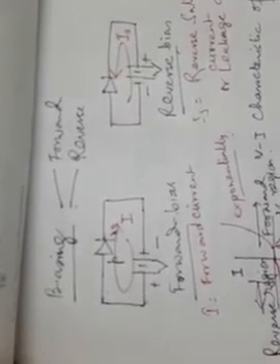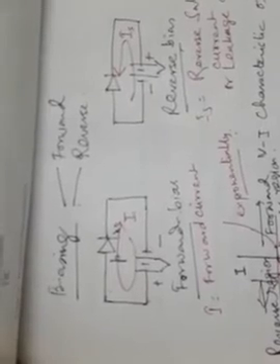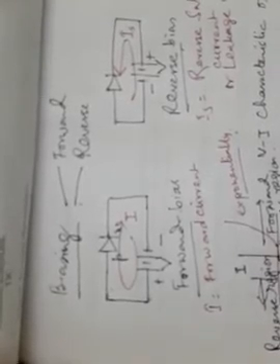This current is because of the minority carriers. You already know this current is because of the minority carriers inside the PN junction device, which is being called here the diode. So this IS or reverse saturation current is because of the flow of minority carriers only, and no majority carrier is contributing to this current.